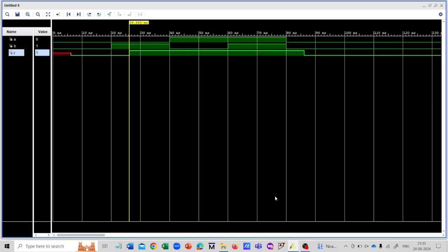So this is a small illustration of how the delays will start emerging when we synthesize combinational circuits, right? So this is one effect of the propagation delay that we are seeing now. That is, because of the propagation delay, the expected output response to an input transition will occur only after some delay.